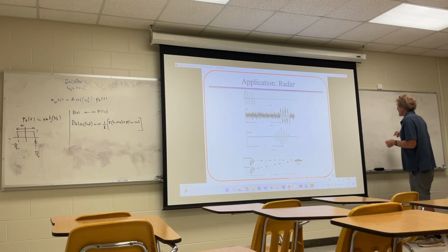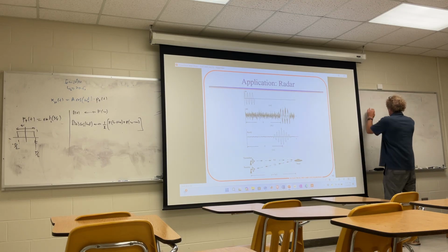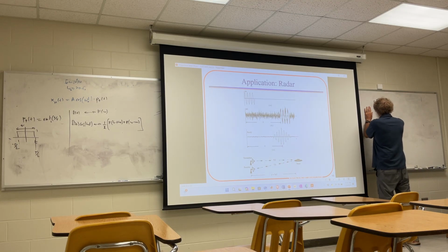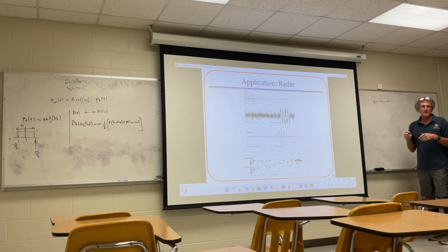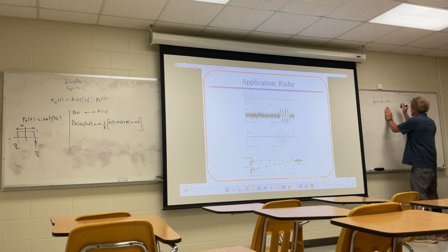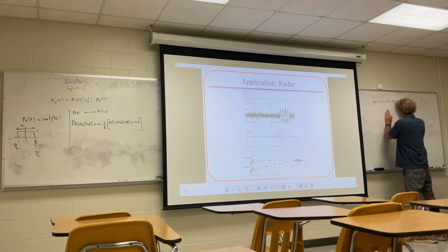All right. Back to this thing. So I take my pulse function. I did this last class. Do you remember what the transform of that is? Sinc. Very good. It's going to be tau times the sinc of omega tau over 2. Correct, class?